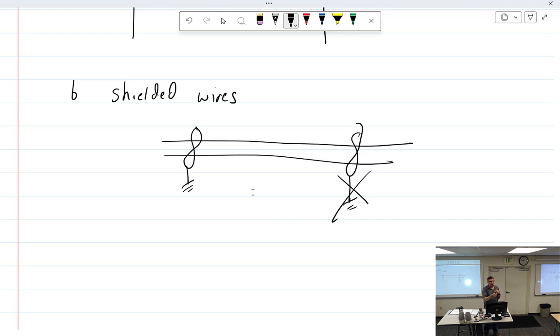When the switch is on, the ground is off. So now I just have a wire that long going from this high frequency generator making sparks into my cockpit, not grounded. It's open. So they put a shield wire around it because it is constantly pulsing, and that shield goes around it, and then out at the magneto, it's grounded. So it's going to take those impulses, go into the shield, and go back outside and ground to the magneto.